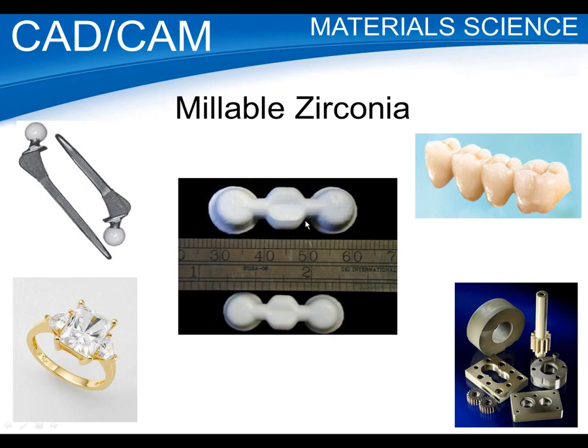So this is significant and nothing that you could really control by hand. Well, but for CAD-CAM, it's a piece of cake. So for CAD-CAM, you just dial in that shrinkage factor. So the manufacturer, when they make the zirconia disc, they've determined the density and calculated that shrinkage factor, and they're going to provide that for you.